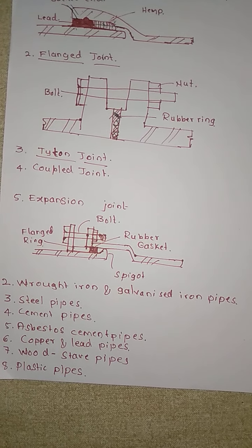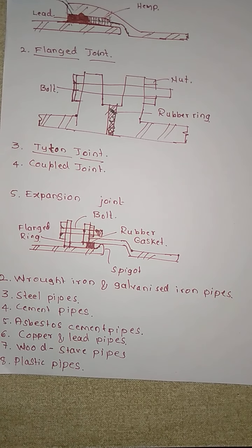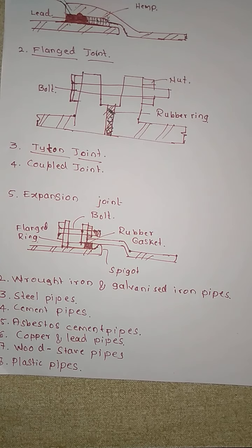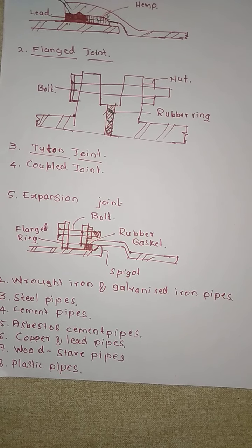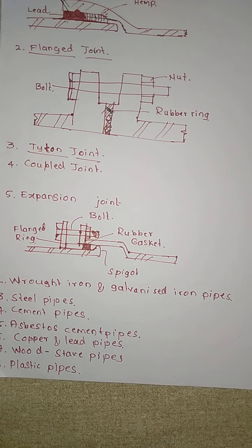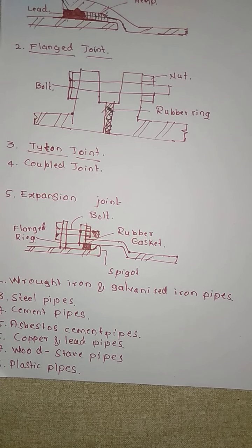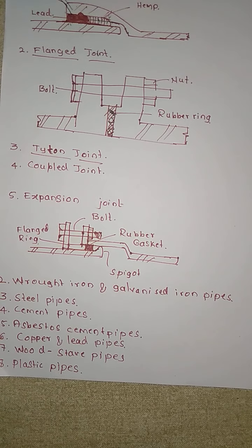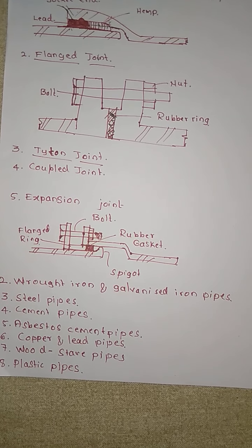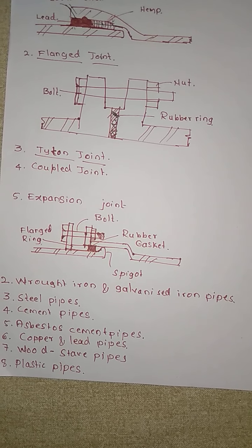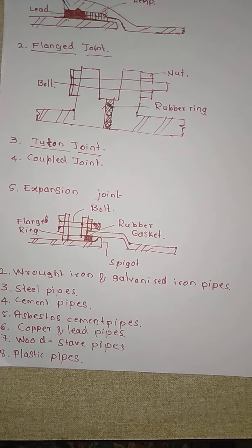Plain cement pipes are used under heads up to 7 meters, while reinforced concrete pipes, that is RCC pipes, normally can take heads of around 60 meters. For higher heads, pre-stressed concrete is normally used, and reinforced concrete pipes are used only for large water supply lines, but they are suitable for the distribution system.